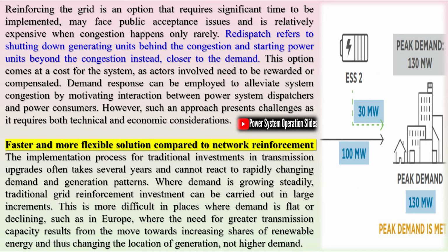Frequency and inertia support: BESS and converter control provide fast frequency response and synthetic inertia. Adaptive protection coordination: protection settings adapt when flows and angles change due to VPL operations. Reserve and ancillary services: VPL resources can provide reserves, ramping, or black start support as part of coordinated operation.